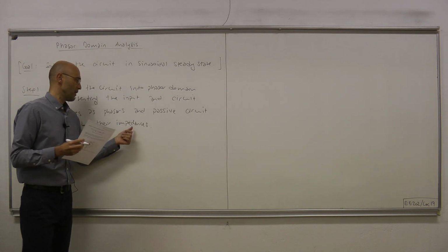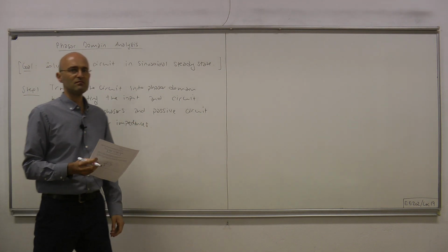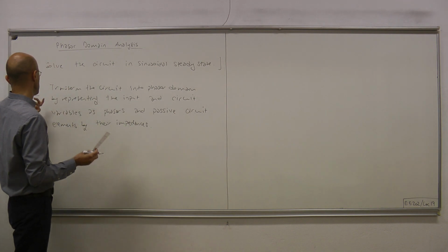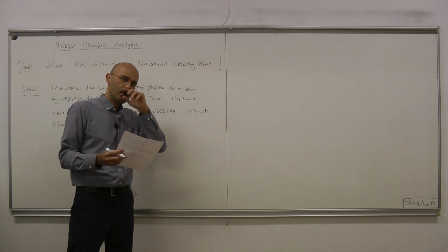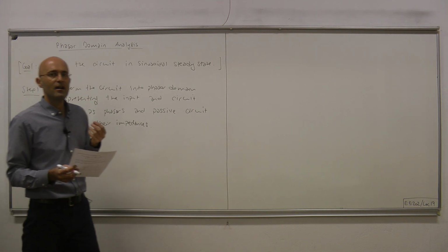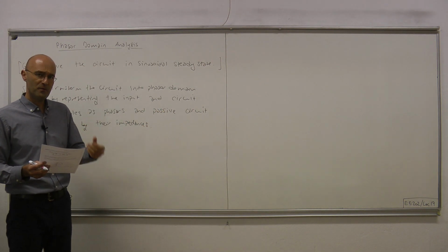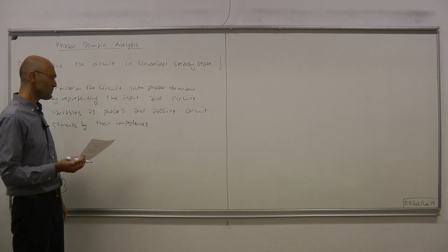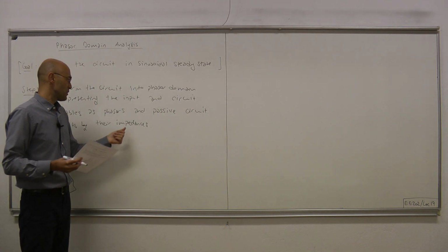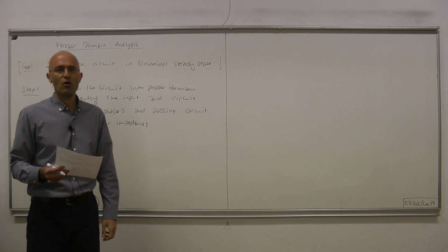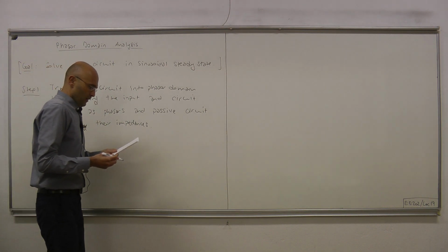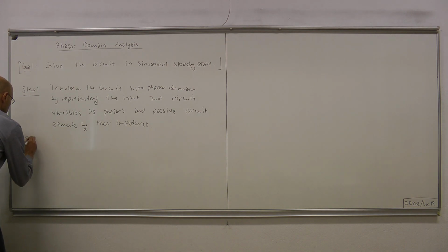Now, since impedance means just generalized resistance, after this step, from the original circuit that we're given, you obtain a sort of LTI resistive circuit. The only difference from the classical LTI resistive circuit is that currents and voltages and also the resistances, which we're now calling impedances, are allowed to be complex. Other than that, there's no difference whatsoever.